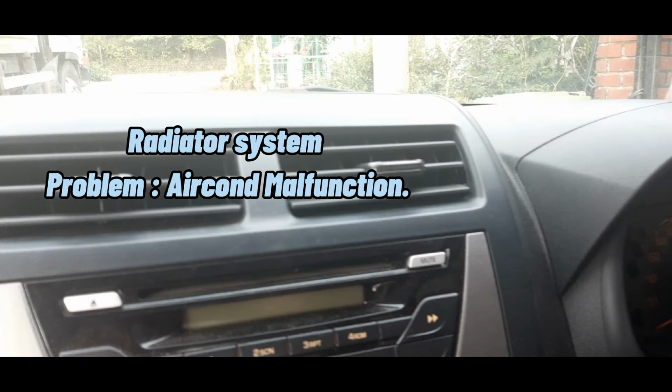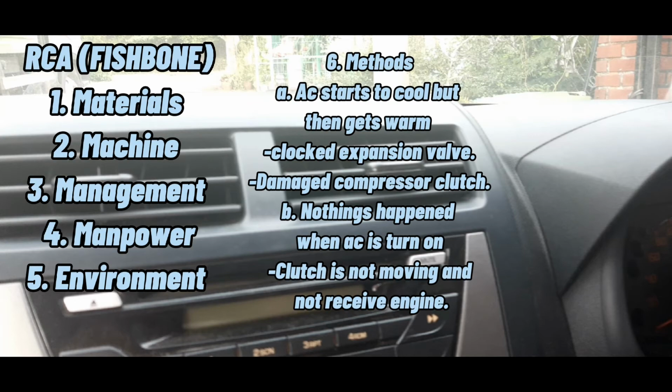Next is the radiator cooling system, which is the aircon malfunction. This is due to the clogged expansion valve, and therefore it affects the AC, which starts to cool but then gets warm.